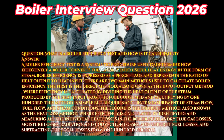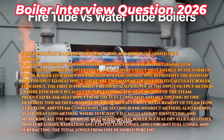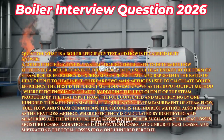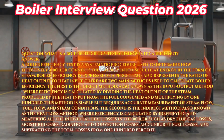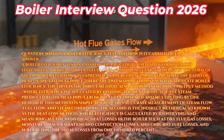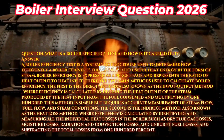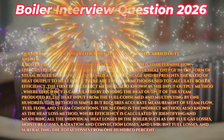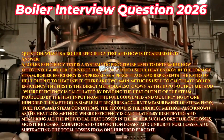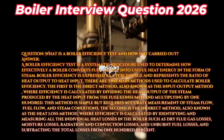The first is the direct method, also known as the input-output method, where efficiency is calculated by dividing the heat output of the steam produced by the heat input from the fuel consumed and multiplying by 100. This method is simple but requires accurate measurement of steam flow, fuel flow, and steam conditions. The second is the indirect method, also known as the heat loss method, where efficiency is calculated by identifying and measuring all the individual heat losses in the boiler, such as dry flue gas losses, moisture losses, radiation and convection losses, and unburnt fuel losses, and subtracting the total losses from 100%.